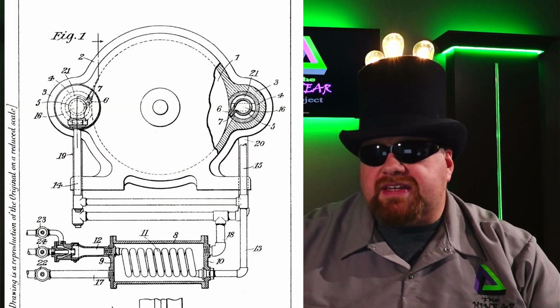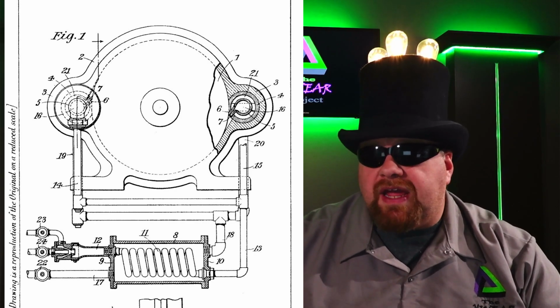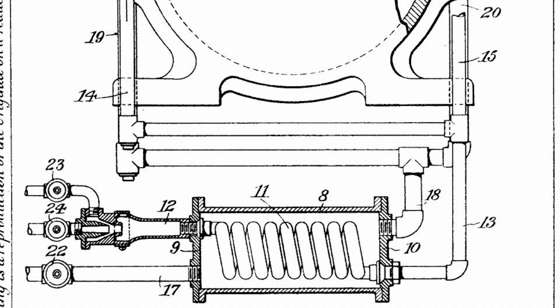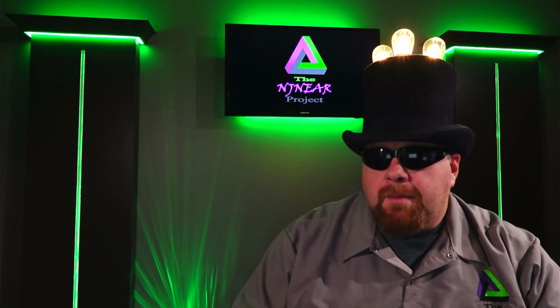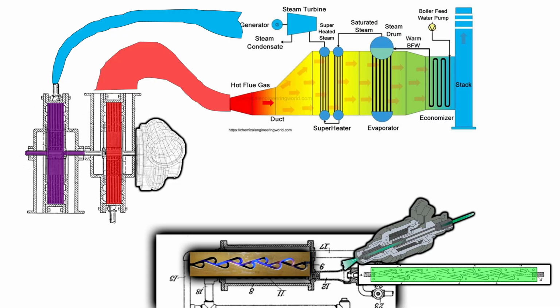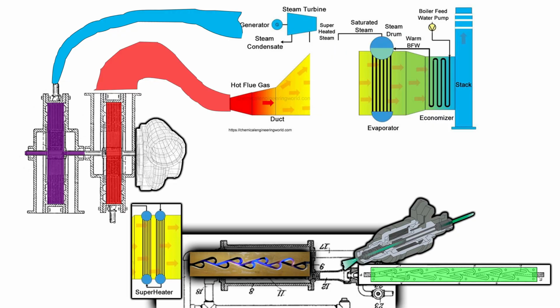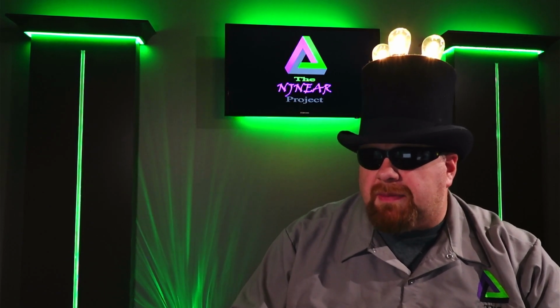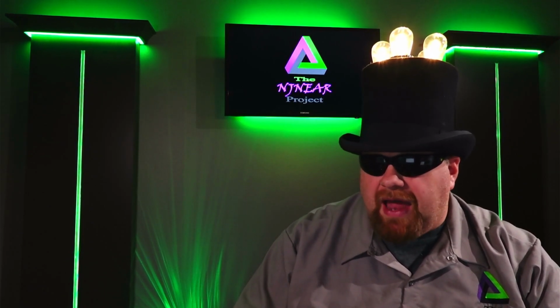I also think we can take a look at one more Tesla patent, 186084. This container is basically a superheater. There is a combustion chamber here and the hot exhaust gas enters into a coil and steam enters the surrounding chamber to be heated by the coils before entering the turbine. By incorporating a Tesla valve that would have a flame traveling through it and encasing that valve with a chamber, we could remove the superheater from the heat recovery steam generator and use the combustion chamber to serve this purpose in a similar way to what is indicated in this patent.